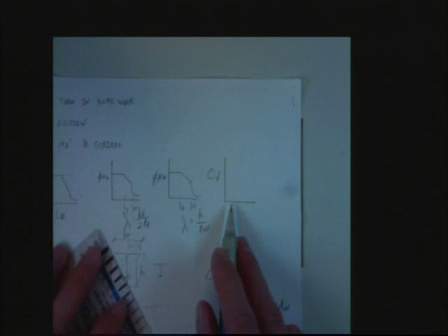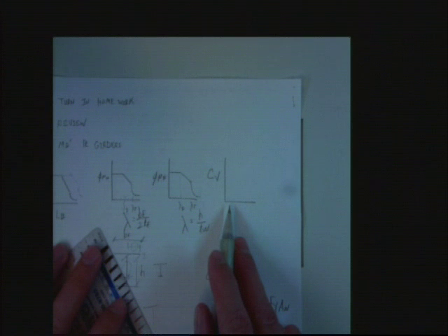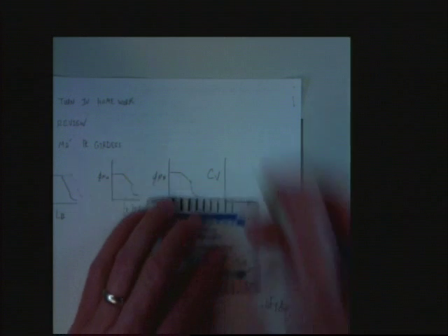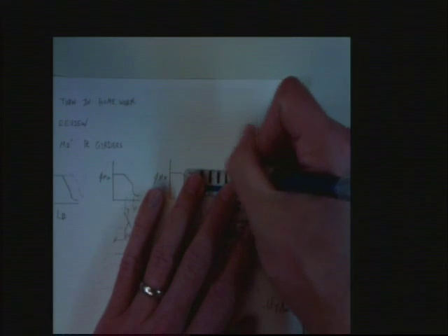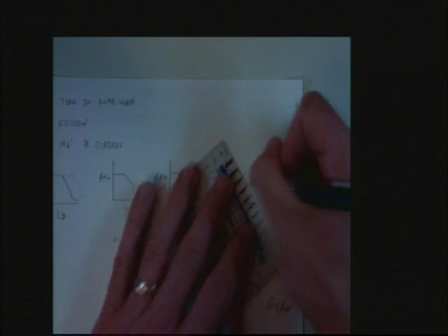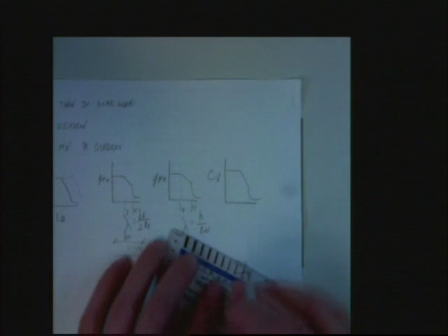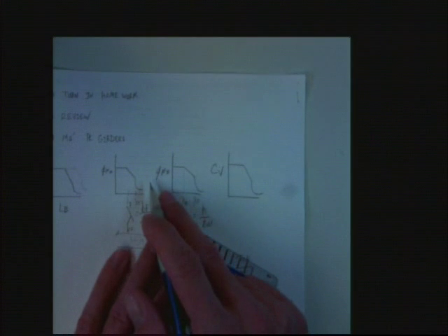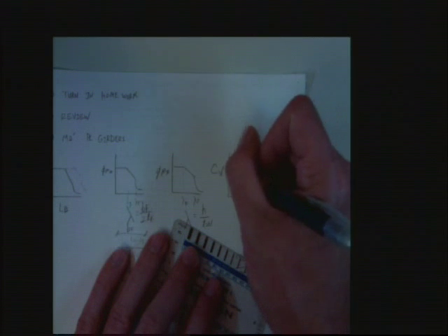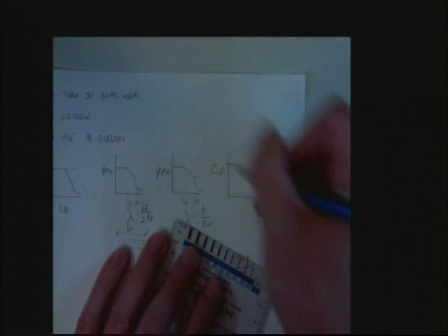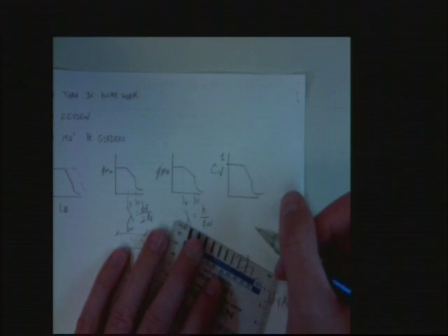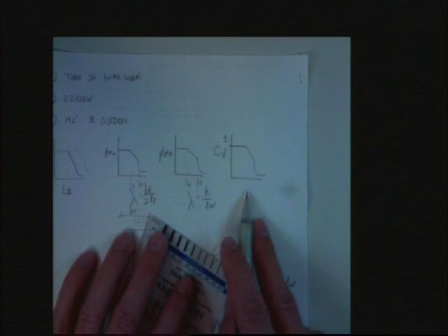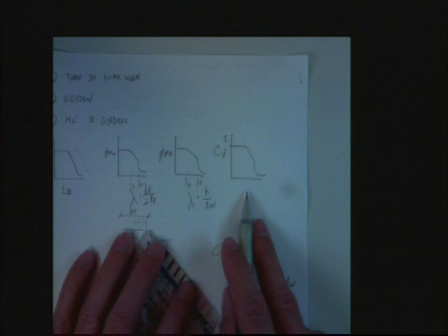So what's this final Snail chart look like? A snail, of course. It's got a flat part, it's got a linear part, and it's got a non-linear part. But this is different. It's not phi Mn anymore. It's C sub V. And what's the maximum value up here? Does anyone know? 1. Very good. And what is the x-axis? Slenderness. Smart. Yeah, that's right.